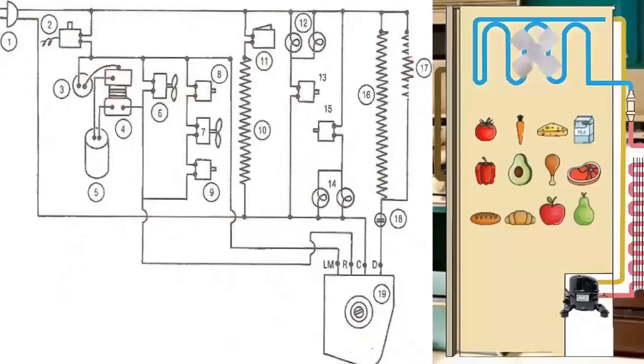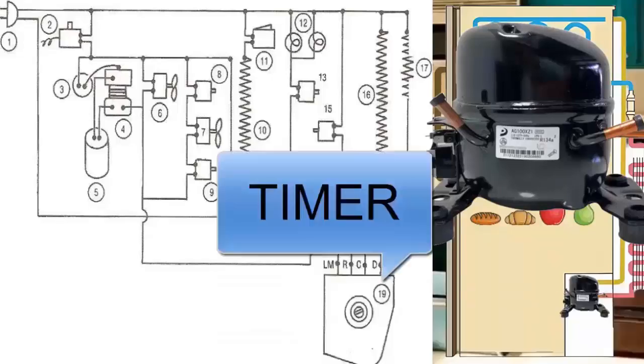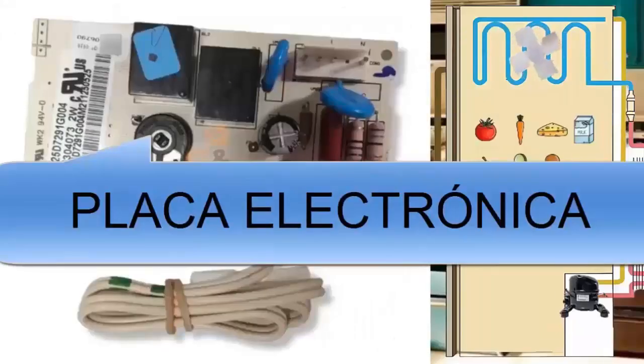4. Verify the defrost cycle. Observe if the refrigerator turns off the compressor for several minutes, indicating it has entered the defrost phase. During this cycle, the compressor and fan should shut off, and the defrost heater should turn on to melt the ice.